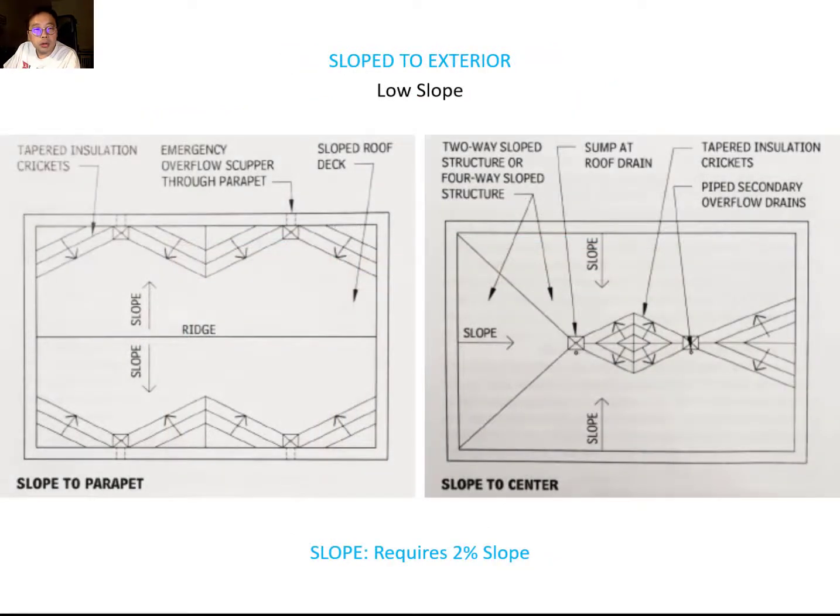So you can see how you can design the drainage system. This is higher, and then this is higher, and then you have the drainage system at the edge of the roof, and you can also add a roof drain in the center of your roof, so it is easy to get the water out when you provide 2% slope.